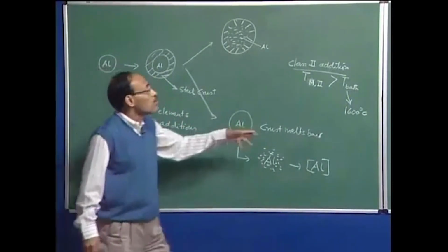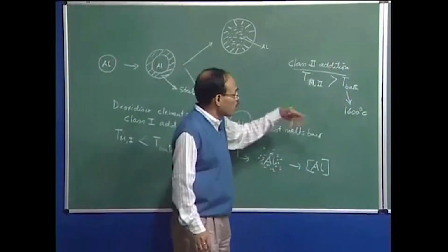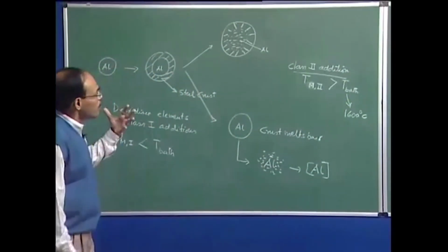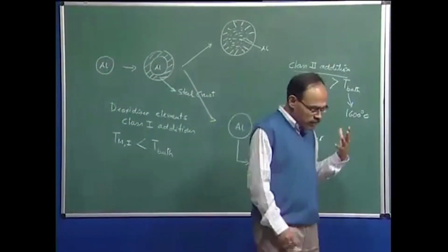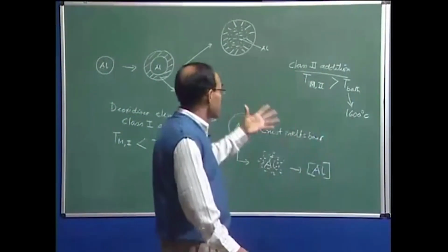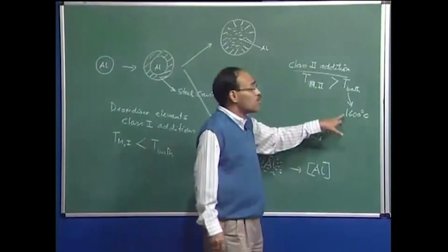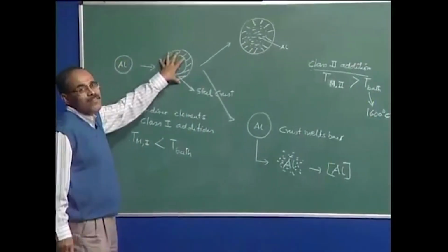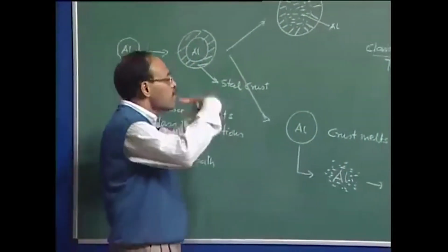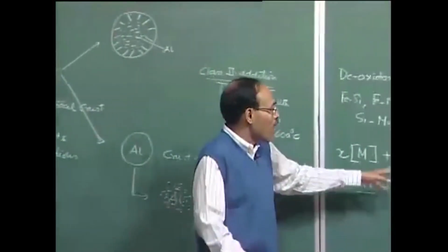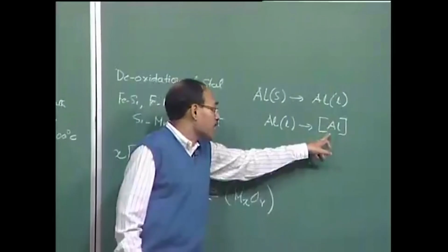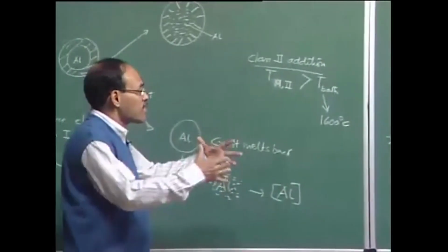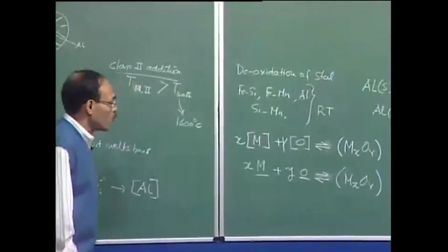On the other hand, if you are talking about, for example, ferromolybdenum, then ferrovanadium, then ferroniobium, etc., these types of additions are not going to melt but dissolve into steel because their melting points are greater than that of steel. But these features of crust formation will be observed everywhere, and then finally, through melting and dissolution, we are going to have the material in the dissolved state, and it is under this dissolved state that an interaction with oxygen is going to take place, as a result of which the oxygen in the bath is going to be continuously decreased.